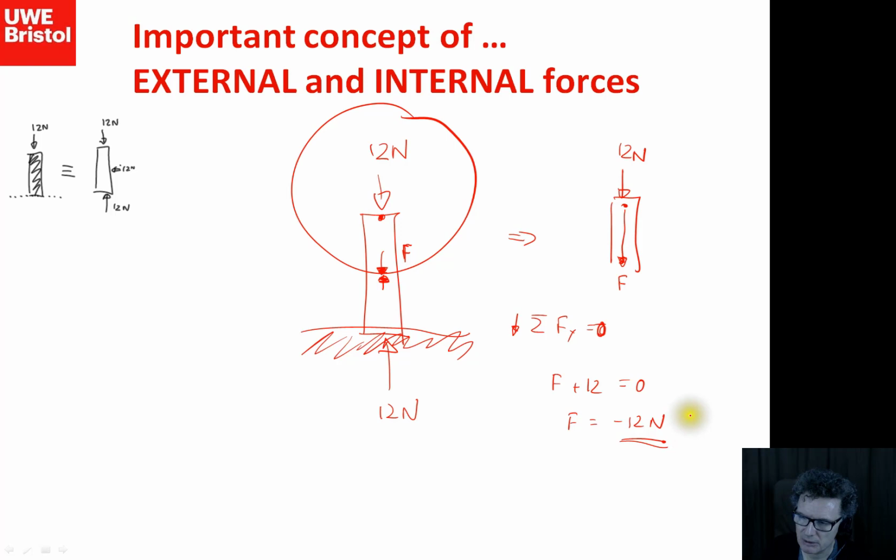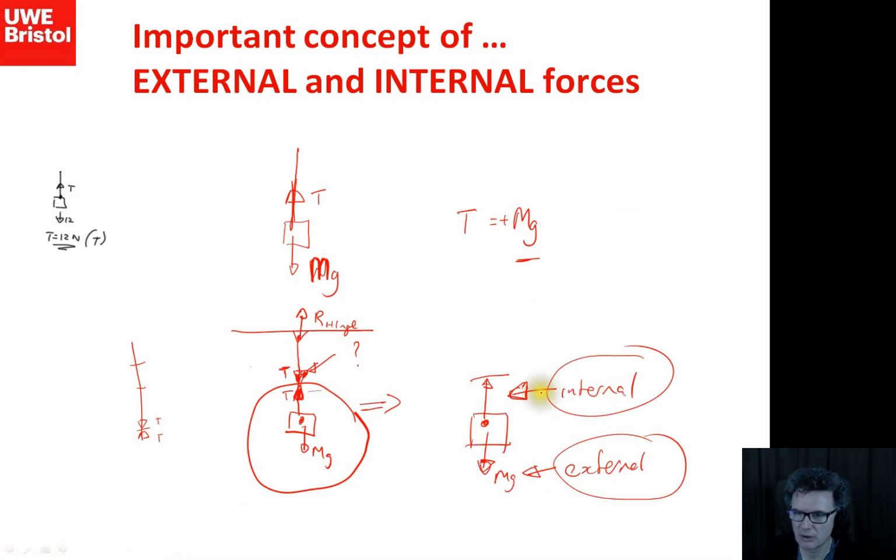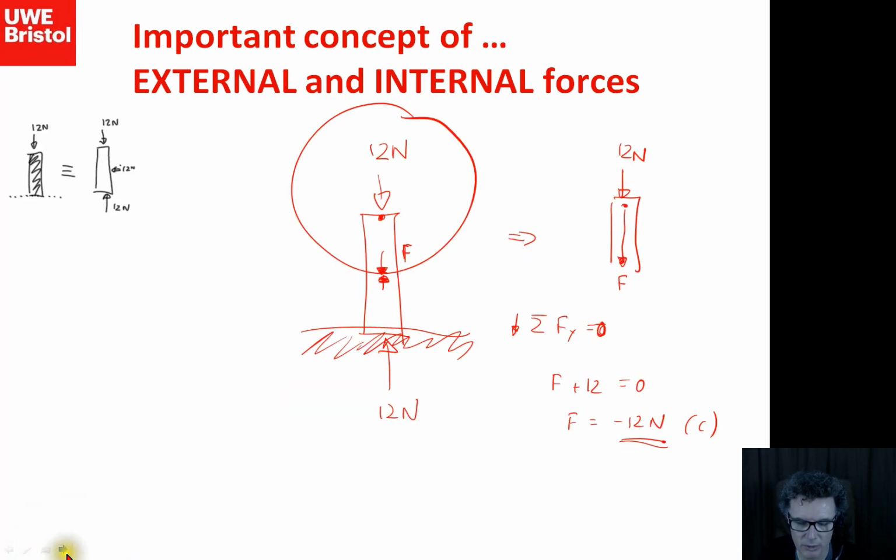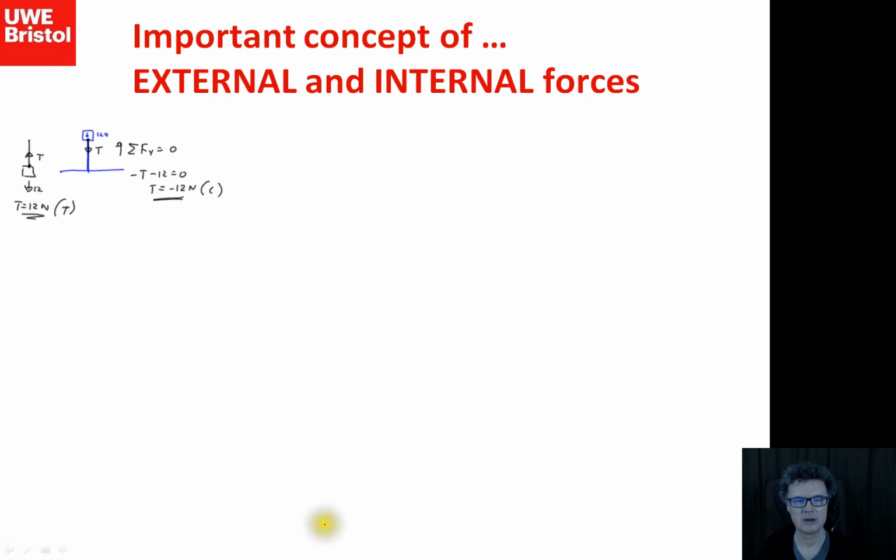So I'm going to say, as a hypothesis, if I get minus internal forces, it's in compression, and if I get a positive force, it's in tension. And we find that that works even when we get into more complicated framework scenarios.